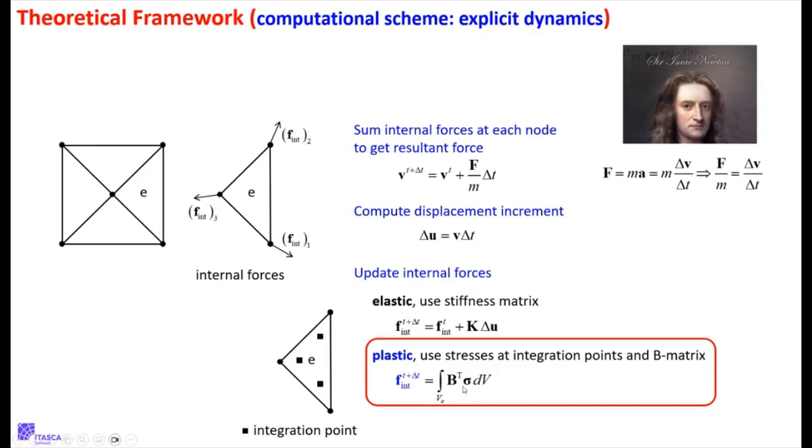And then to check if it all makes sense, if I take my plastic solution with that crazy integral that I implemented, and if I set the strength of the plastic material to be infinite, well, it should now behave like an elastic material. So to test this system, I make it infinitely strong and I can run two models, one that uses the stiffness matrix and one that uses this. And they should give me exact same answer. So it's cool because I have a way of determining if I implemented things correctly.